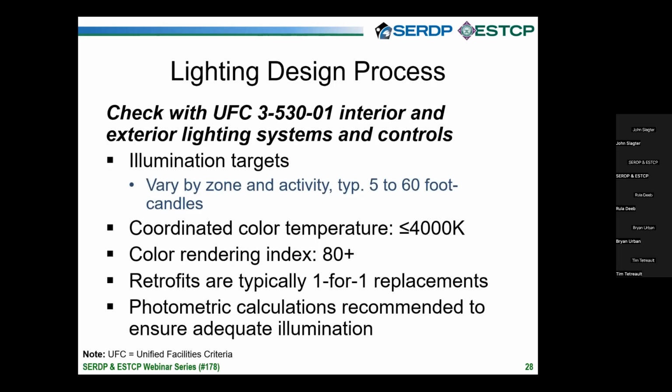Typically, the retrofits are 1-for-1 replacements. So again, the design is usually not that hard. And normally you want to do photometric calculations to make sure you hit those brightness targets. You can either hire a lighting designer to do that, or in many cases, the lighting vendor will do these for you. In our case, we had a full service lighting vendor, and as part of their sales process, they would do these calculations and create maps and do all this work up front. So ask your lighting vendor if that's an option, and you might save a lot of time.